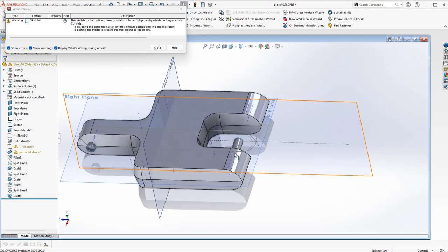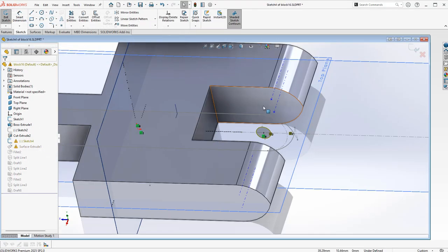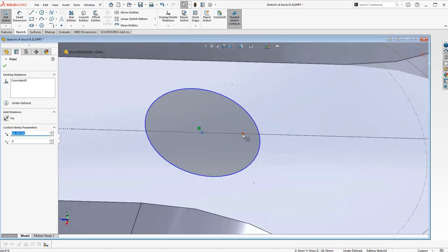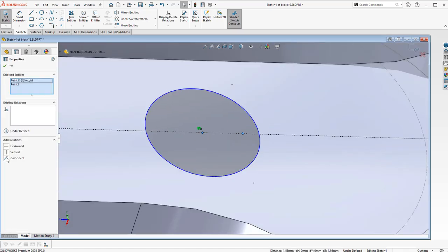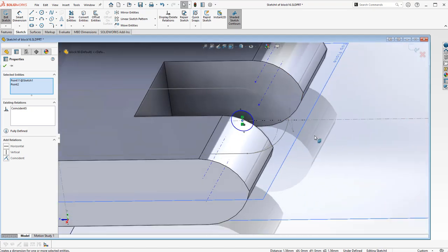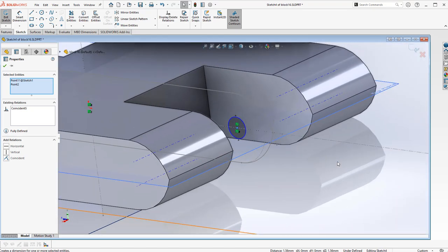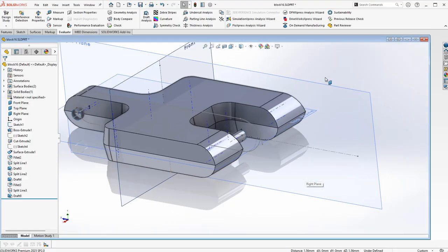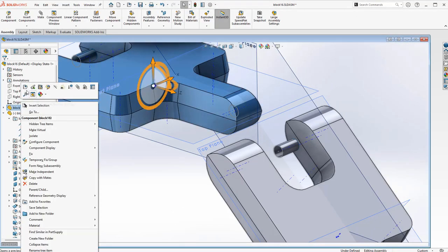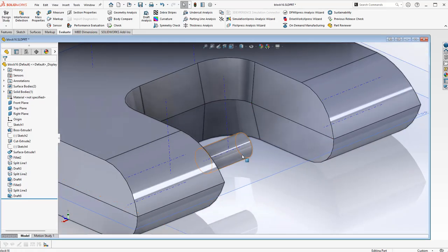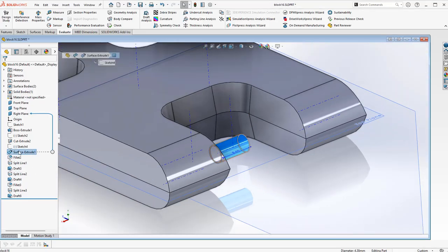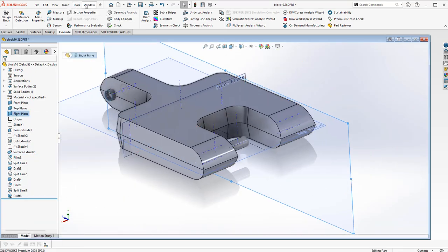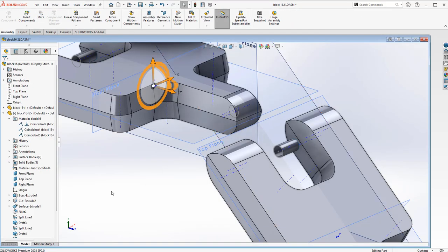Now we've got that sketch. Easy to fix. Now I just pull it off to the side. I can see what reference it had tried to constrain to. This circle is extruded as a surface to establish an axis where I can manage building the assembly without fail. So what I did is I had hidden this surface extrude, so I unhid it so I could fetch the selection out of the assembly.